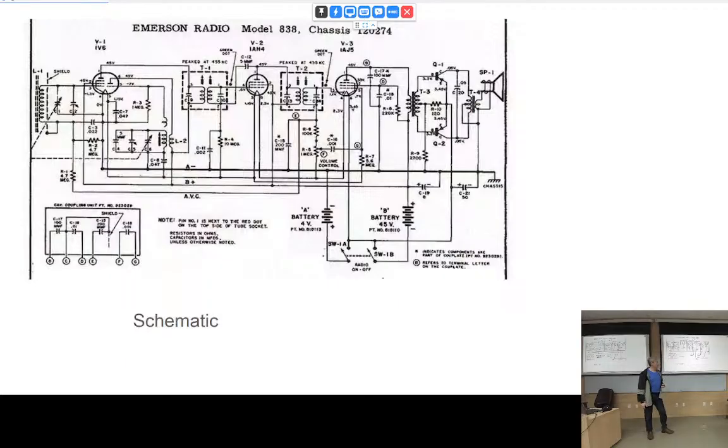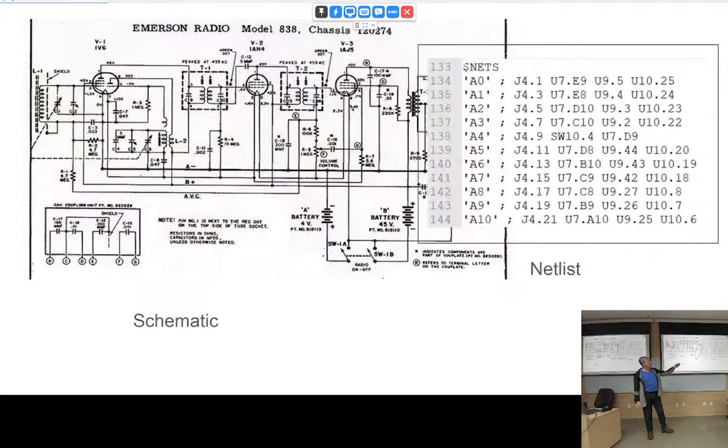And now this is a little bit complicated to use, so that's not what I would give somebody on the factory floor. I'd give them what I call a net list. A net list is a text, where each line of the text shows all the wire, all the pins. It's a list of pins that should be connected together through wires.